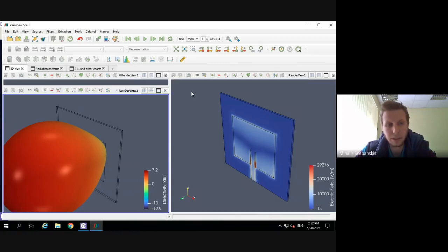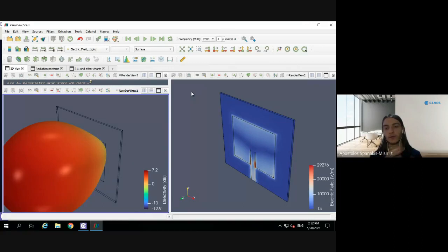Yeah, in FreeCAD, where I loaded, for example, an SMA connector, you mean? Yes. You can load an SMA connector, you can load some patch antennas, and you can also create your own component. You can, for example, model an N-type connector or some sort of microstrip antenna, whatever. And you can actually save this, and then you can import it from the components library.